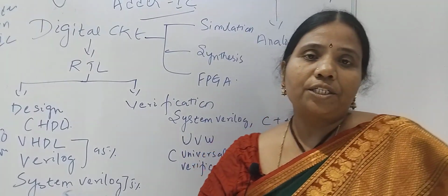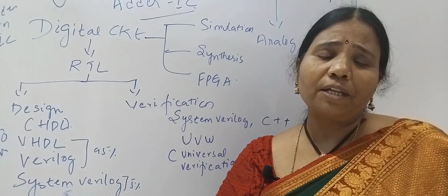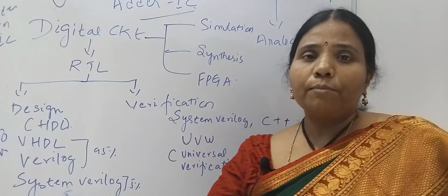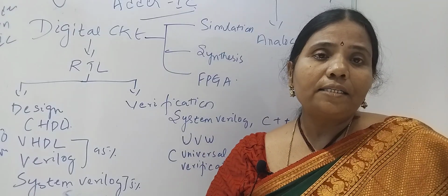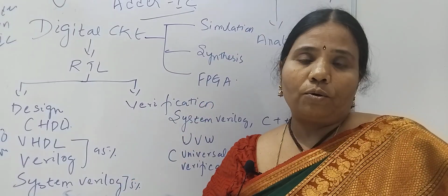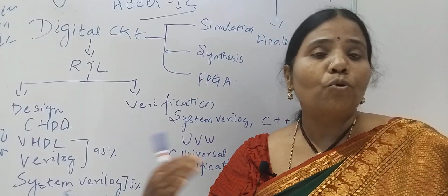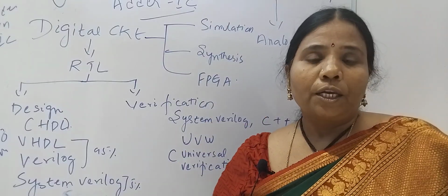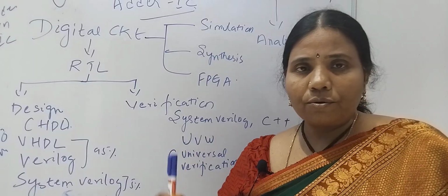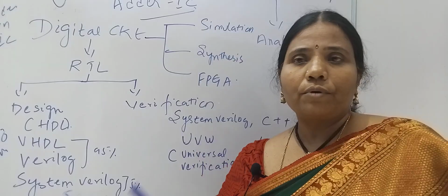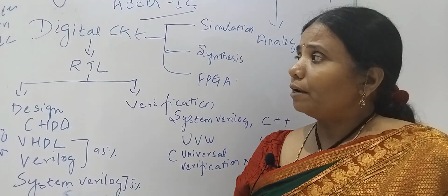Once they receive the specifications from the customer, the company people will start working on the circuit. How will they start? After taking the input, a team of engineers will sit and analyze the adder circuit, and write the design of that circuit on paper. Then the design and analysis of the circuit is made into code form using the software tools they want. Usually they use tools like Xilinx Vivado, Cadence or Synopsys, and programming languages Verilog or VHDL, to develop the program for your adder circuit.